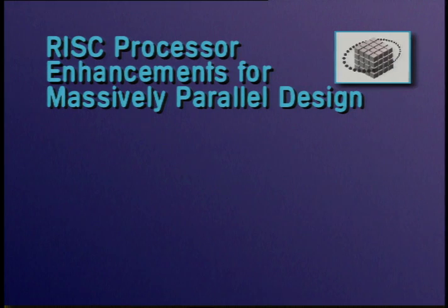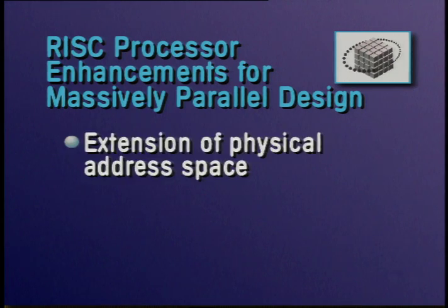Fortunately, there are ways in which the microprocessor can be enhanced with appropriate supporting shell logic. A globally addressed memory subsystem designed with the objective of scaling to more than 1,000 processors requires a very large physical address. Even a large workstation memory by today's standards is small compared to that of a fully configured CRAY T3D system. When data cannot be found in the local data cache, the cache miss invokes an external memory reference.